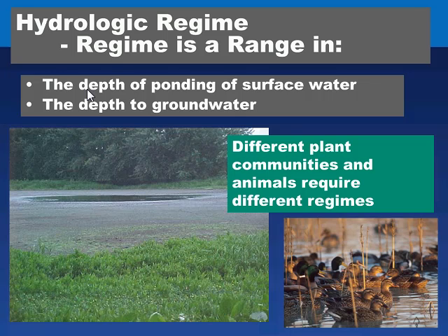We've got surface ponding. That ponding range might be from 12 to 18 inches, and it's probably closer to 12 inches. We have a surface saturated regime, and then in the foreground we have a wet meadow regime with groundwater at some distance below the surface. The point is that these three separate regimes respond to three separate functional types for wetland plant communities and the associated wildlife habitat.